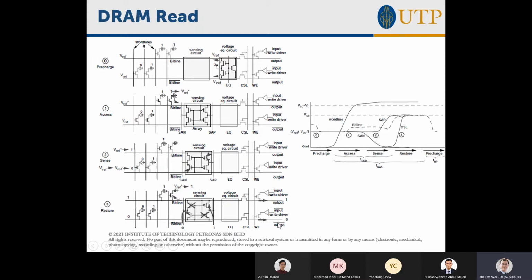So this is how the read is done. But when the value at the output is there, remember this word line is still turned on. That means this logic 1 line has just now discharged a little bit, raising the charge here slightly higher. Then when you turn on this line, it suddenly charges all the way to logic 1. When this is logic 1, it is going to charge back the capacitor here; the restoration happens here. And the converse is true. If this happens to be logic 0, it's going to discharge this capacitor all the way to logic 0.